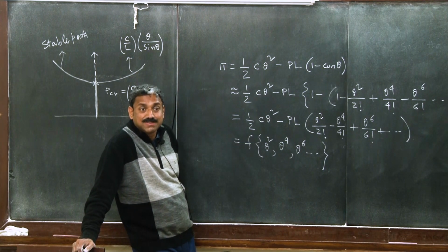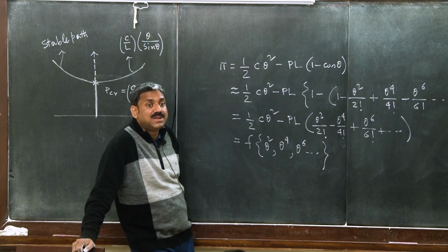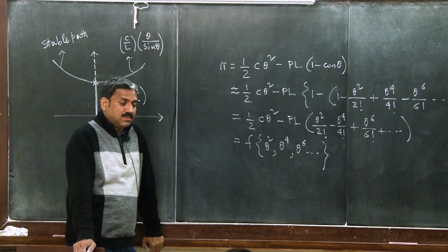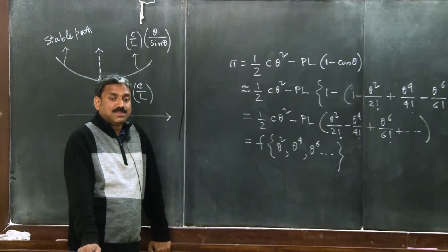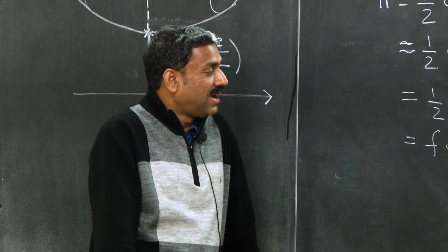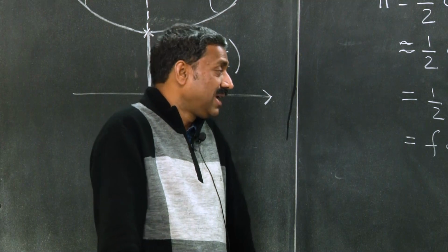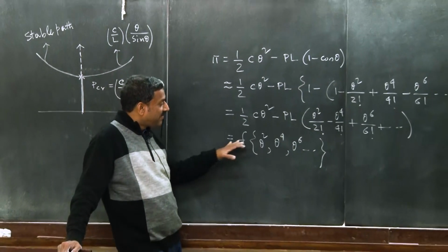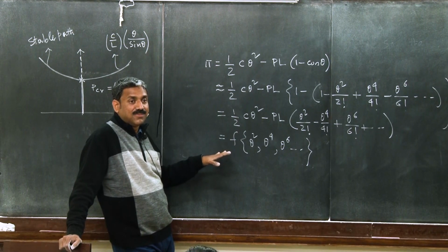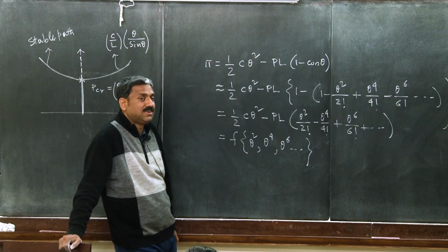By looking into the expression of the potential energy functional, you can comment on the stability behavior of the system. That is what nowadays you see in Hutchinson's concept of the energy landscape theory. When you qualitatively construct that using the probing load technique, you can essentially fit a functional like that. So by looking into this functional expression, you will be able to comment on the stability behavior.